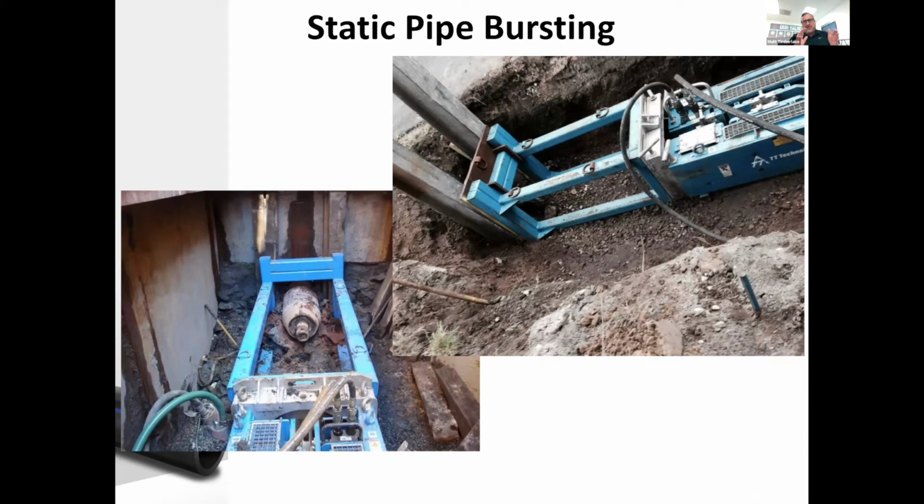As we exert that force to pull that pipe through, that force is exerted against the head wall or the face of that excavation. So oftentimes, in the picture on the bottom left, you're going to see that trench box with those big steel beams, and that's how we're going to spread that force out across that trench. That stops the actual tooling from advancing through the soil column. So that's very important, especially when we get into larger pipe bursting rigs and larger operations.